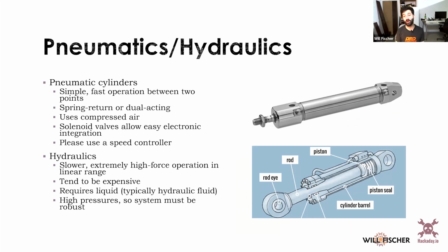Pneumatics and hydraulics are really, really cool and really useful. I use them for a lot of my stuff. I tend to stray away from hydraulics because you typically have to have high pressure pumps to do them. And so they tend to be pretty expensive. But they have extremely high force operation within a range. Pneumatics don't really do ranges very well. They operate really between 2 points, but they can be extremely fast, like scary fast, with relatively high force, which is really exciting. The forces correlate to the pressure that you put into them.